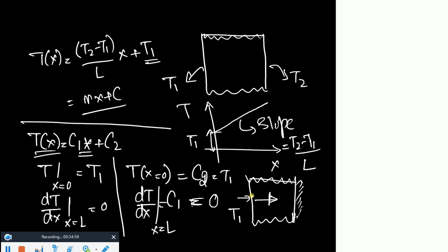You have temperature T1 over there. There is only one dimensional heat transfer which is possible. If some heat reaches this surface, it needs to go out, but that is an insulation. And if there is an insulation, would you be having any kind of heat reaching at this point? Not at all. It means all the points on that wall would be having the same temperature.